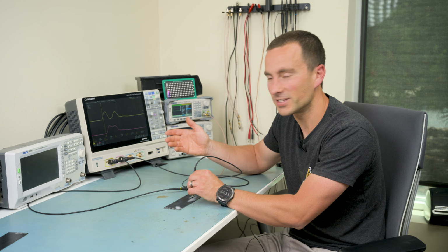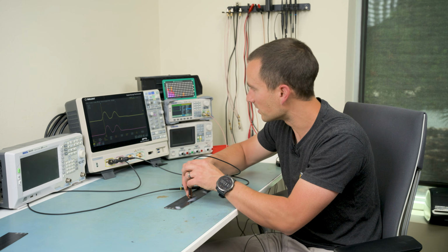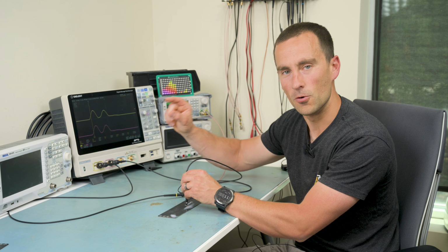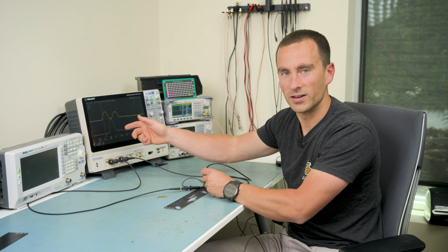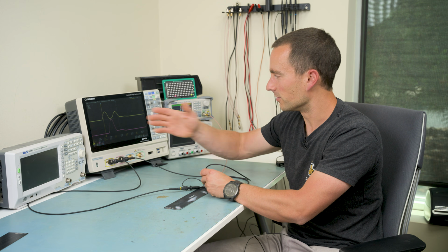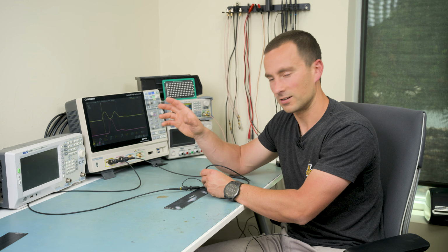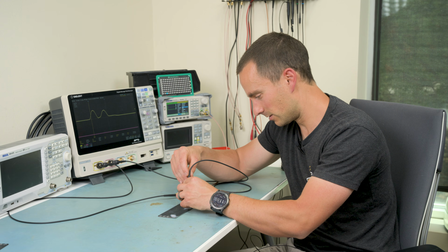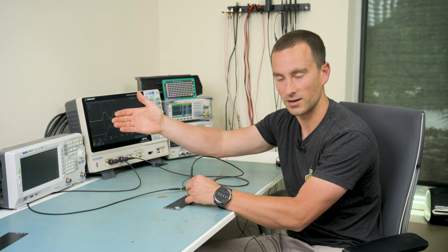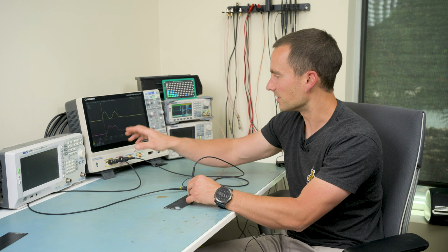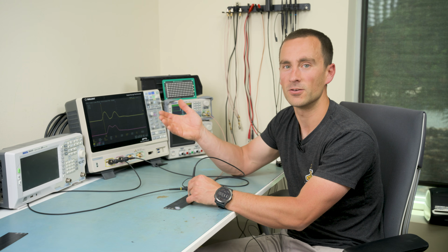What's perhaps a bit interesting is that if we look at the signal going down the line, like maybe here, we can see that these two pulses are only half the height of the received signal. And that's because the received signal is both the signal we're sending plus its reflection added together perfectly in sync. However, when we're somewhere else, those heights are no longer perfectly in sync because the reflection and the signal we're sending are out of phase.